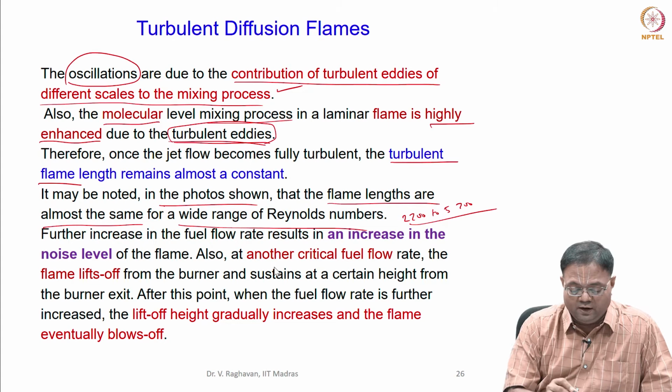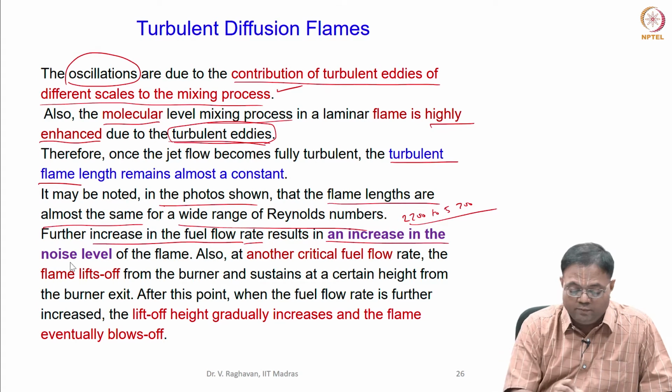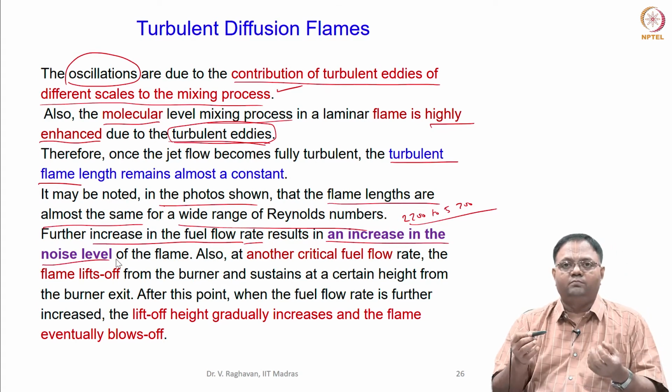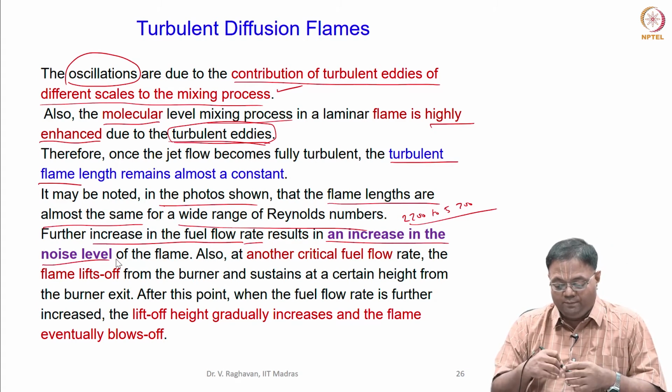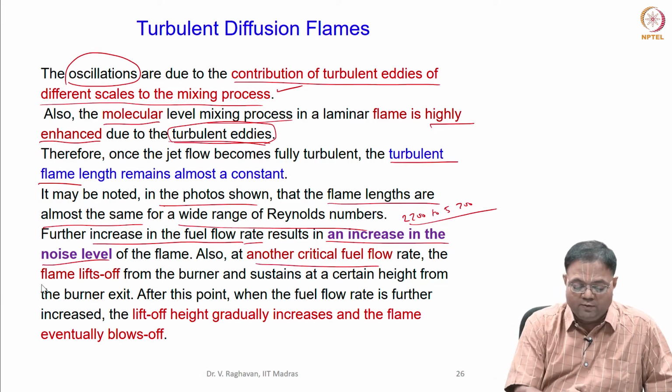Now you can see that when you increase the fuel flow rate beyond this, the flame will be noisier. You see some noisy flame. And there is another critical flow rate at which the flame will lift off from the base.